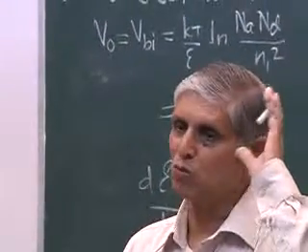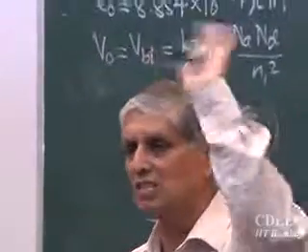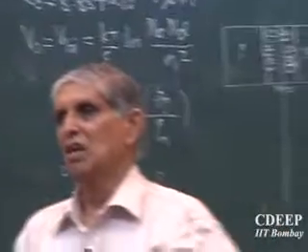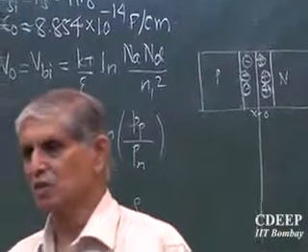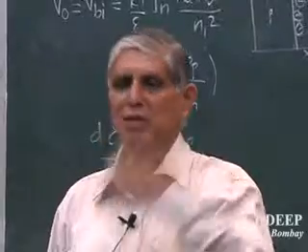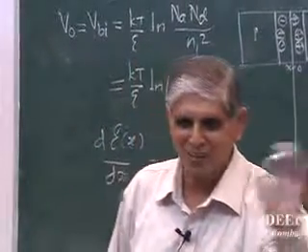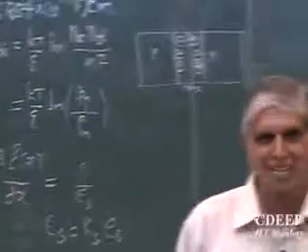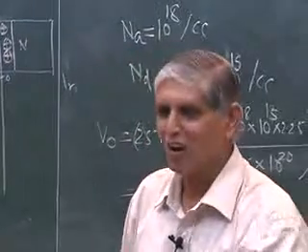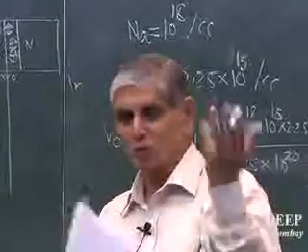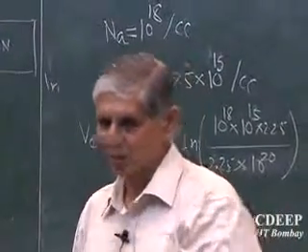Maximum will go up to how much? 1.1 volt, if all density of states are filled. That situation never exists. You cannot dope any material to that extent. What is the reason? The solid solubility of particular dopants is less than NC and NV. So it cannot reach that level, though we may wish it could. This is the problem.